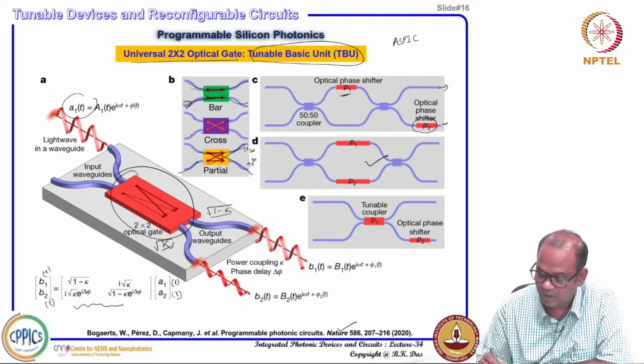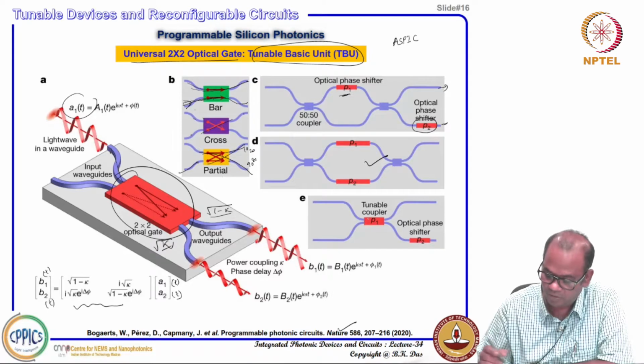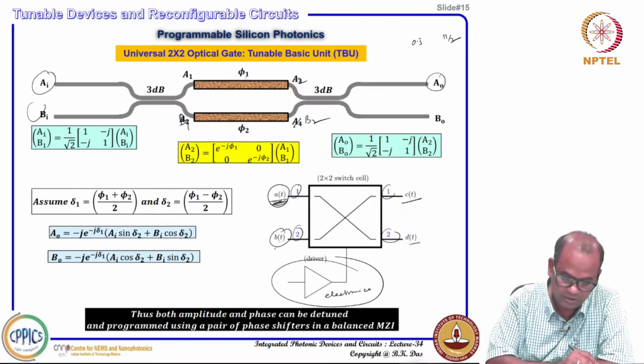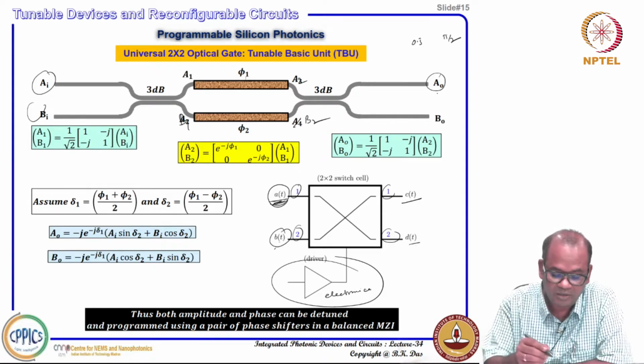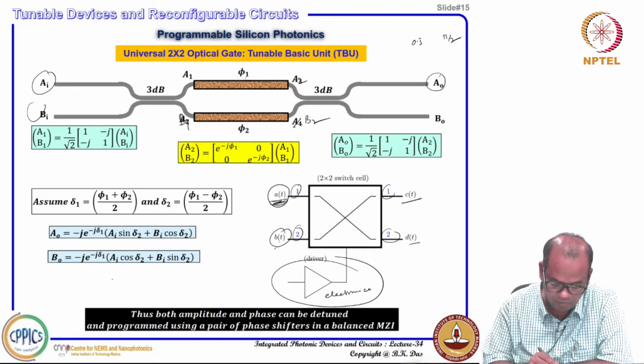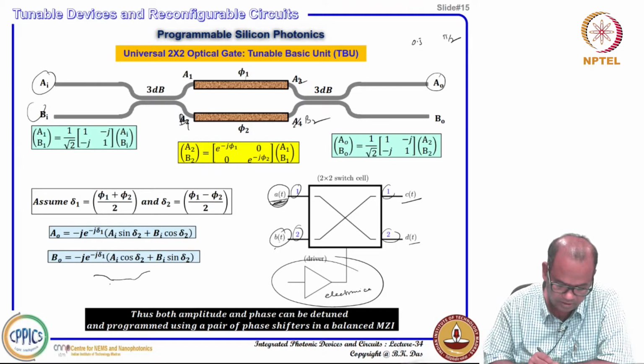And this one, sometimes, instead of going for, so go back to the previous slide, it will be clear. Instead of just controlling amplitude here, you can think of just a simple one directional coupler. You know directional coupler, you can design it like LC. So, if you launch here, normally everything should come here, and if you launch here, everything should come here.